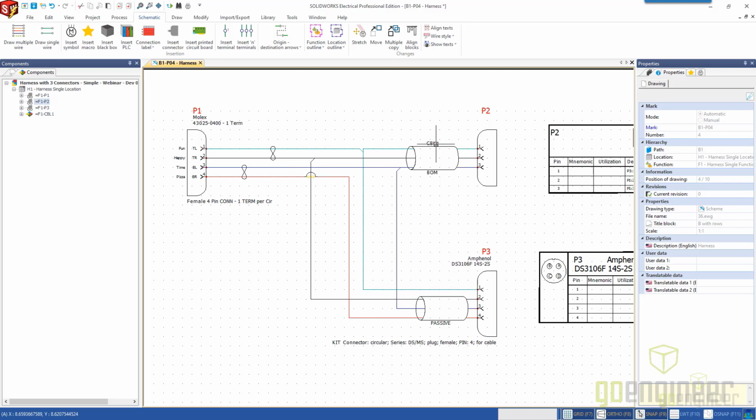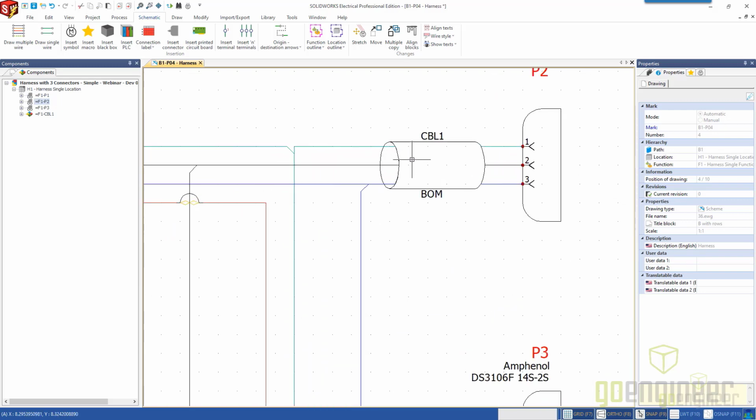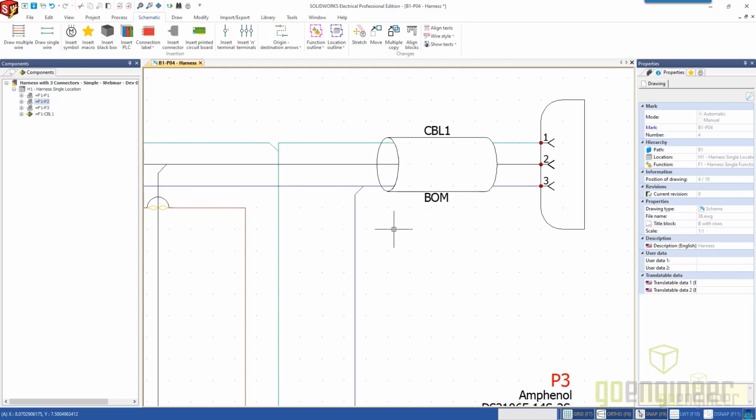I would obviously assign a manufacturer part to that, but you can create a symbol that kind of illustrates something, and I kind of got fancy with mine. You could just do like a loop. You don't really have to do the wipeout and all that goodness with it, but this would allow that to show up in the bill of materials there.